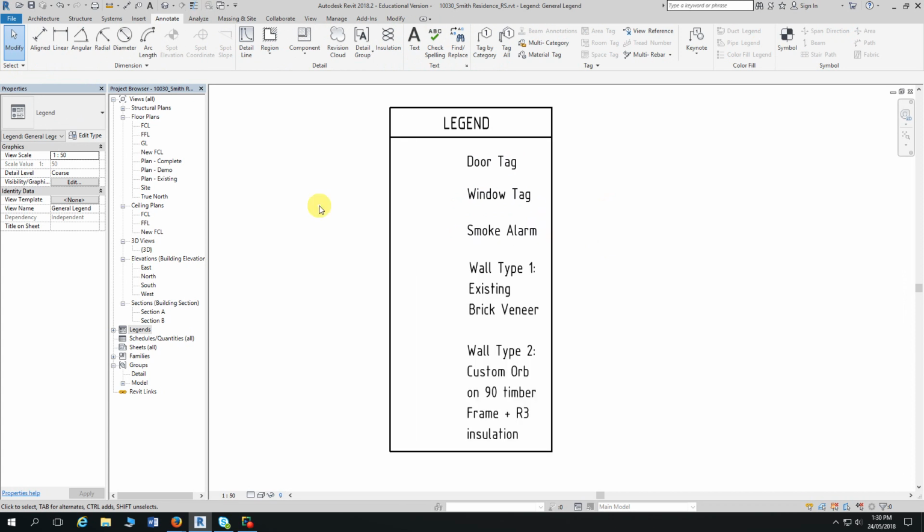Right, so the text is in. Now, if you change your thick lines or thin line setting, you should be able to see the thickened outline of the line work you've drawn. Can I also get you to change the detail level of this view to medium, please?